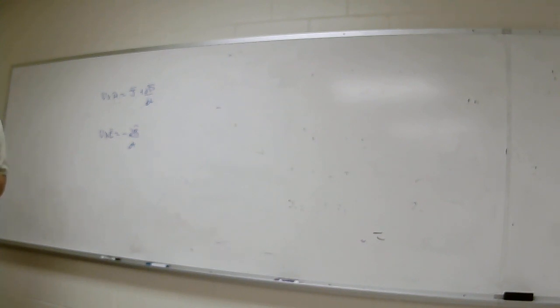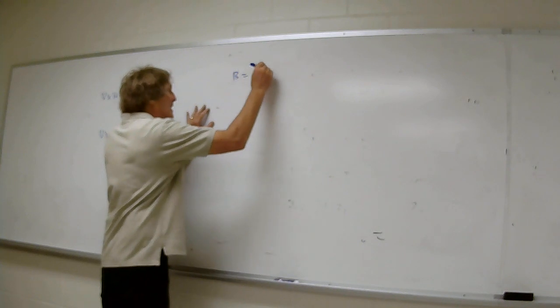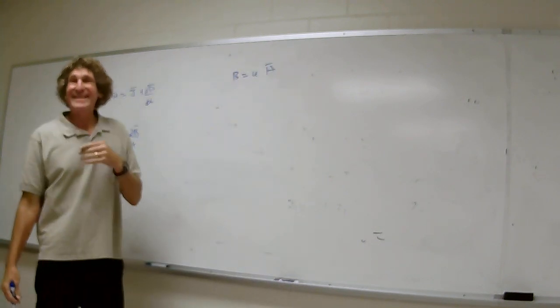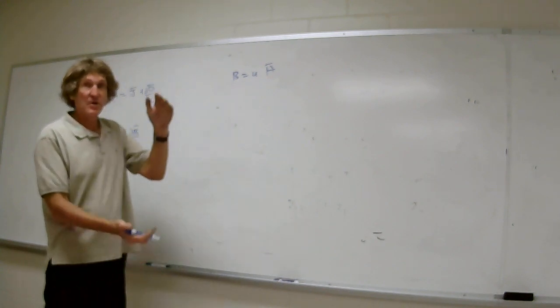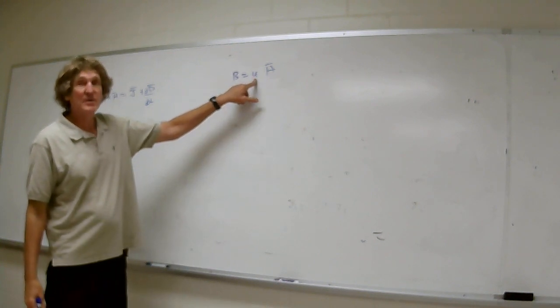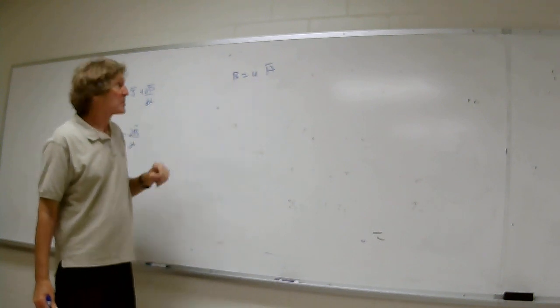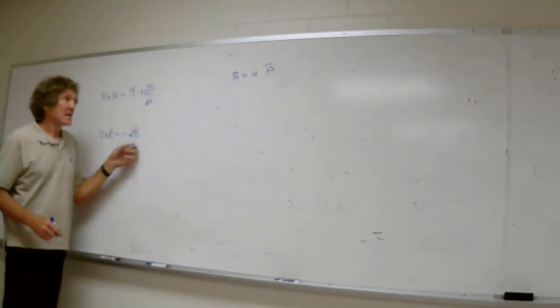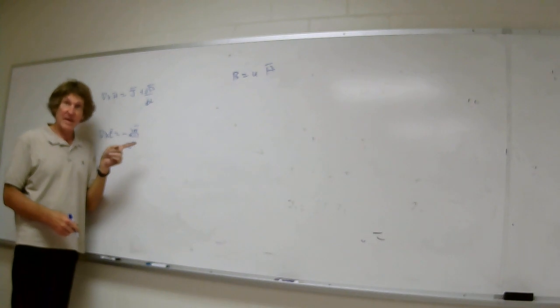In H. All right? Problem is, a lot of times the mu, for instance, we have B is equal to mu H, right? Well, in a time-varying situation, or if it's transient, or if the B field's or H field's value is going to vary orders and orders of magnitude, mu will not be a constant. So now the derivative of this with respect to t is not just mu naught times dH/dt. Now you have to take a derivative of mu with respect to t times H plus mu times the derivative of H with respect to t.